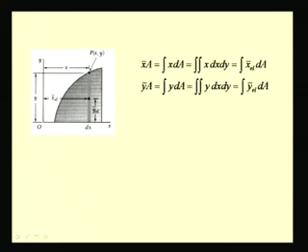We can write x bar A as integral x dA, which is a double integral if we take a small differential element of this form. But now, since we have taken this rectangular element, it becomes a single integral with x bar of this rectangular element times dA, where dA is the area of this thin strip.